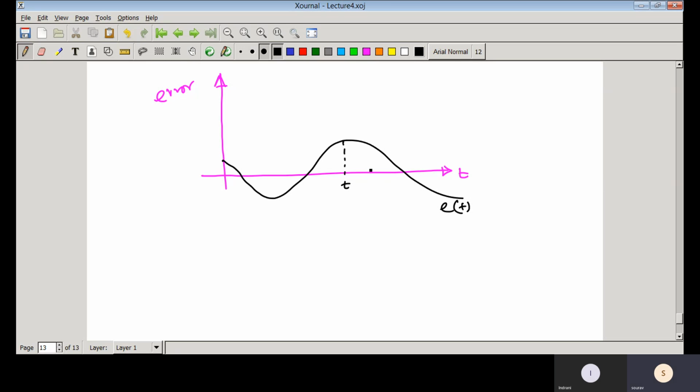at t. Now you can see that the integral controller basically gives you the integral of e(t), that means it gives you the area under that curve. So this is actually that integral part. Here you are at t, so the integral part gives you the information of the past.